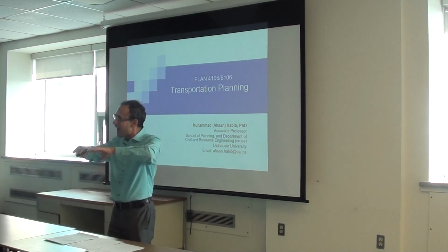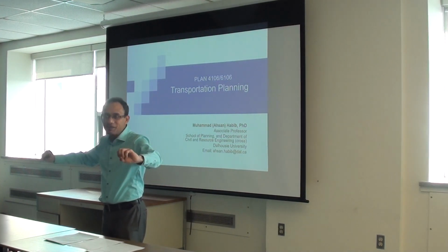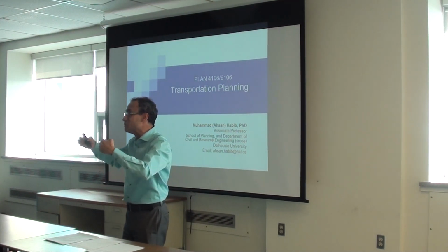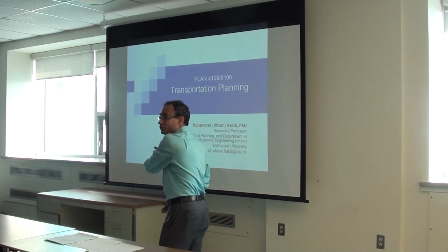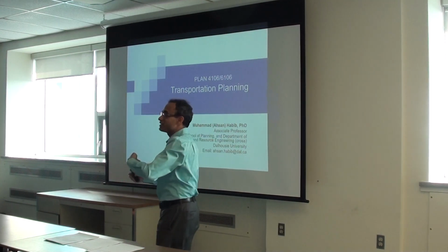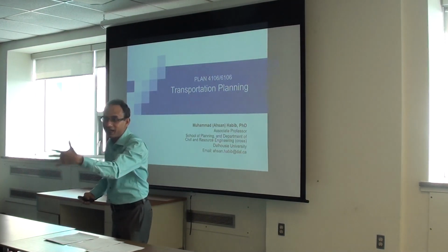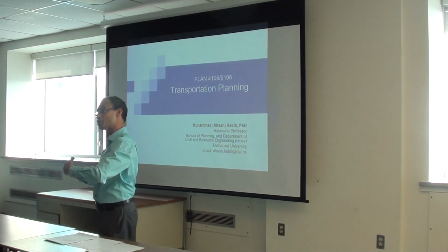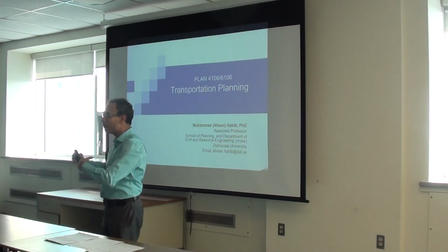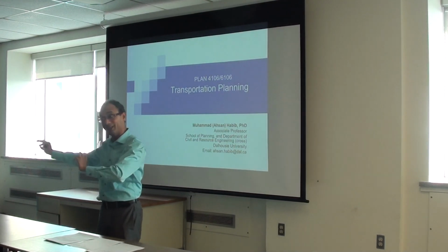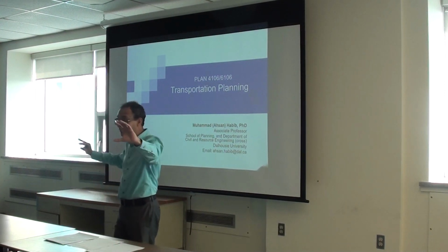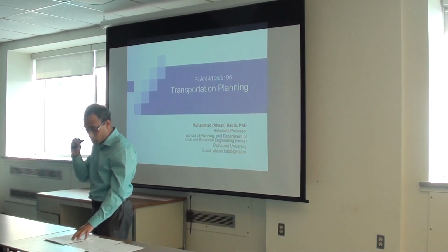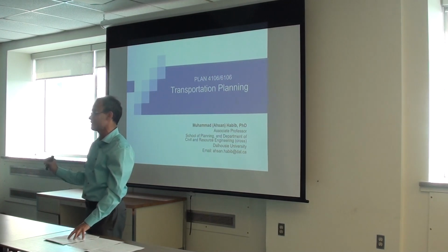So you first get this higher level corridor analysis with some sort of a screening mechanism with certain criteria, which corridor you feel is most beneficial, that serves everything that you learned from my different lectures, that serves the travel demand, that has a higher coverage, for example, more residential area or destinations being served, or cost, constructability. Like if we are looking for some dedicated portion of that corridor, not the detailed design, very high level, the corridor level, which corridor to prefer. That's what I'm saying, select the most promising corridor through a screening process.